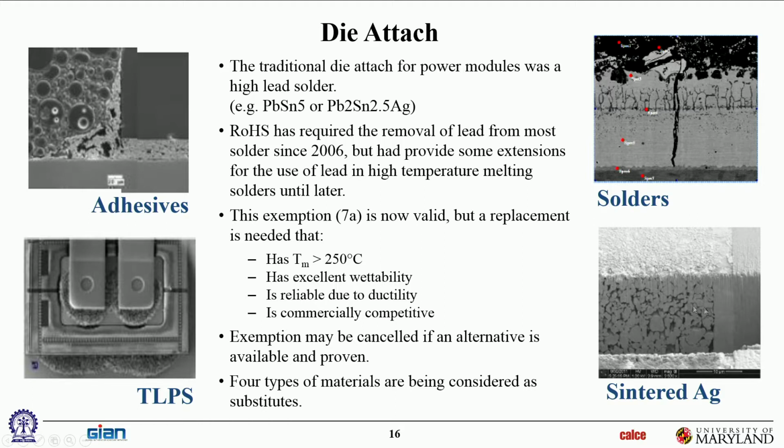Once they bond, you now have a semi-porous material, and the higher the bonding pressure, the lower the porosity, but it's a semi-porous material that's now just directly bonded silver. Now it's not going to come apart until you reach close to the melt temperature of silver. In solder, the problem is you're always close to the melt temperature of solder. By close, I mean above half the melt temperature on a Kelvin scale. Silver is 900 to 1,000 degrees C melt temperature. So now you've got a high temperature material. The disadvantage is it's a porous material. And as you know, porous materials have mechanical fragility, right?